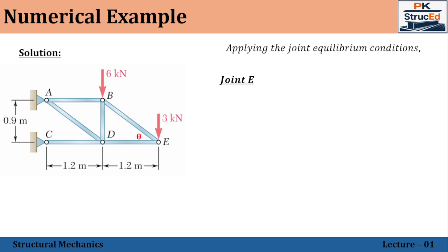Now, as I told, we are going to apply the joint equilibrium condition directly rather than finding out the support reactions. Okay, let me start with the joint E. So joint E, why we are starting with the joint E, in the sense, we have only 2 member forces unknown in that case. So that is the reason we are going to start with the joint E,